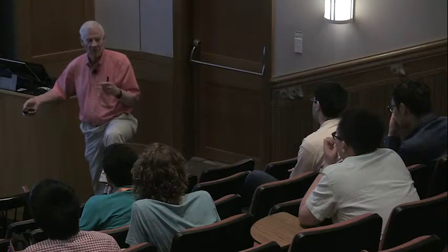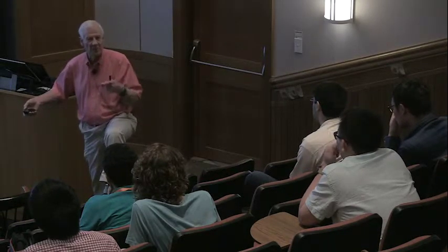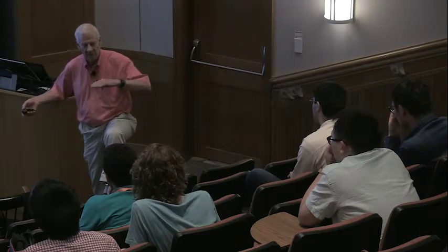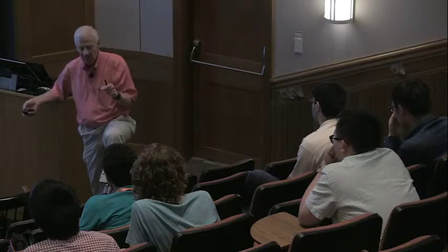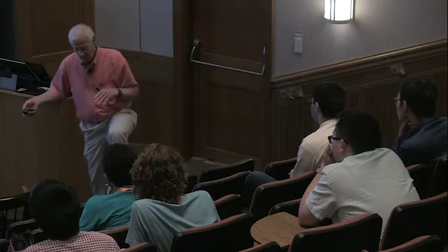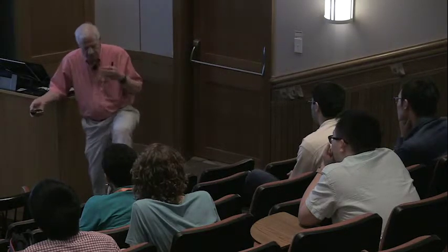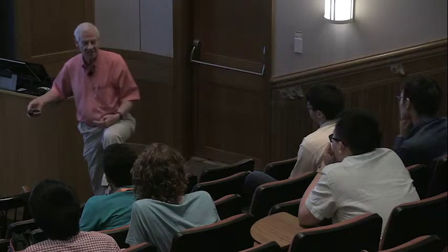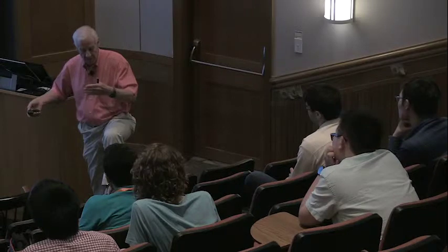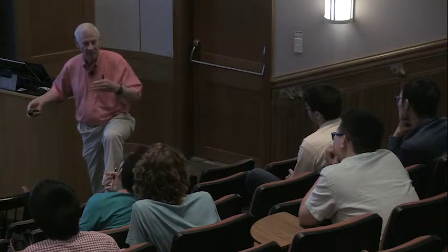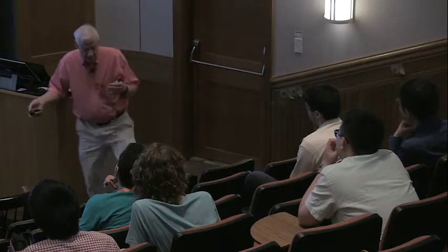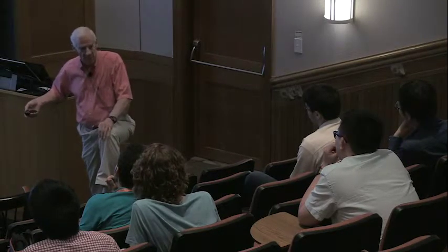When you do tomography, the ultimate spatial resolution is always limited by your number of views. You can't get to millimeter resolution in a 10 centimeter flow unless you're looking over a lot of time and a lot of angles. Because it's math. So why not just take the plane and scan it fast? You get all the resolution in the plane that you want. The only trick is, how do I scan this plane, and do I have a camera that's fast? So there's some optical engineering here. But I think, personally, that tomography in PLIF is not the optimal strategy.